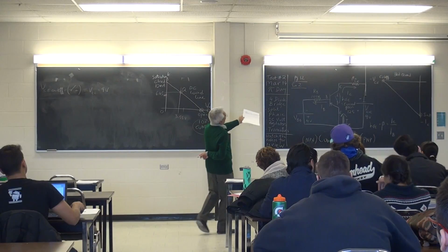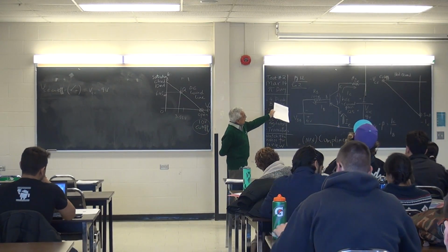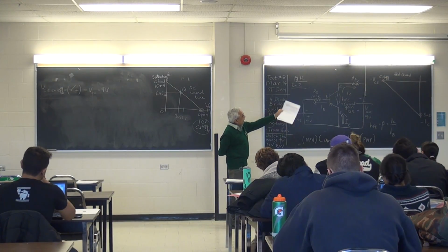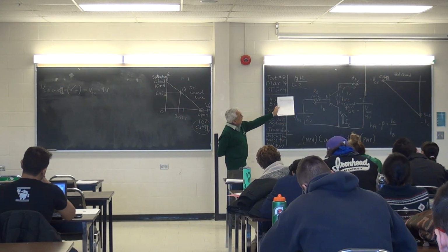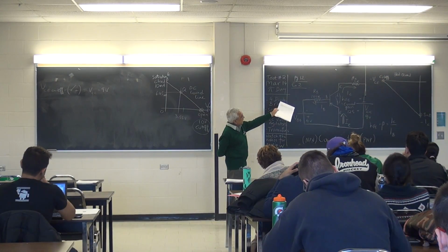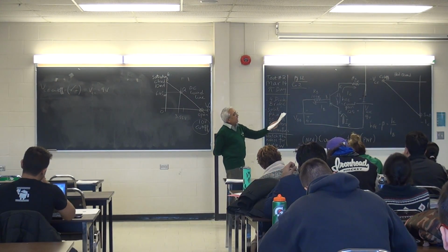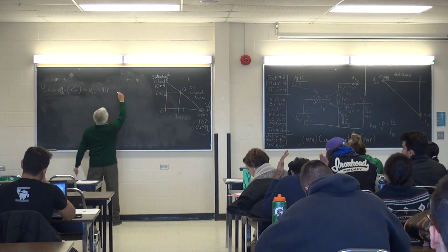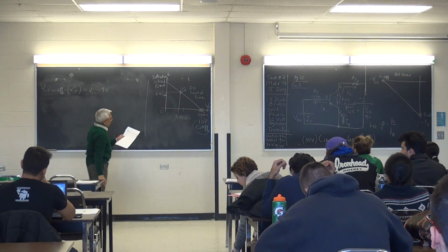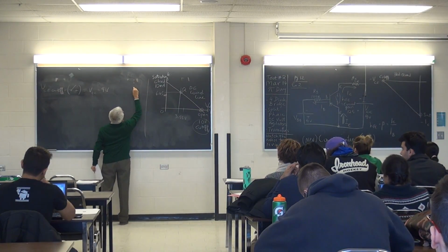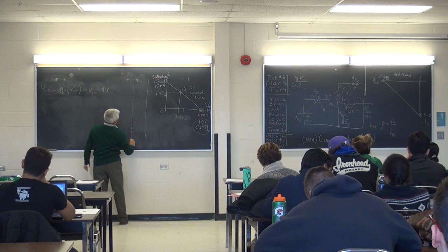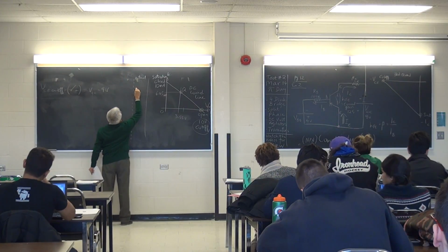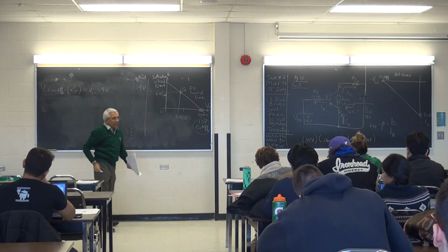So, as you can see, the direction of the currents change, the polarity of the voltages change, and we're doing a lab this week where we build this circuit and we measure all the voltages and currents, and we notice that they are of an opposite polarity. So, what I want you to do is at the edge of your page, draw a dotted line like this and indicate actual, and in this case, write down negative 9 volts.